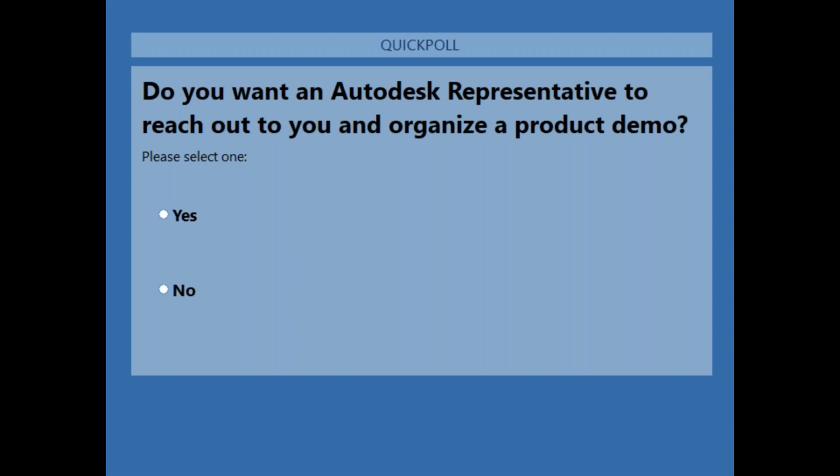There are questions on whether we use Revit MEP for modeling. The plant industry works in the form of a spec catalog. If you are doing piping layout and modeling for a typical plant project, use Plant 3D. In case you're into projects like commercial projects or airport infrastructure, where the MEP aspect is different, there you need to use Revit. Ideally, the two industries and the two verticals are different, so be careful where you're utilizing the two tools. The two tools are meant for two different purposes.